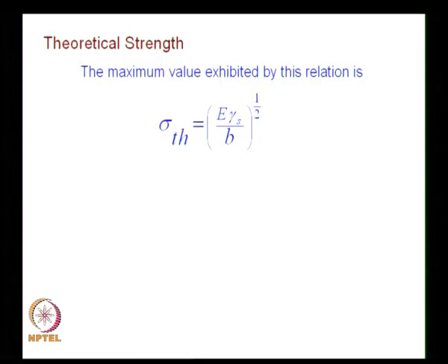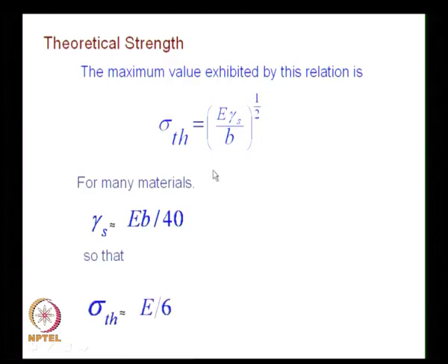People have also found out what is the value of gamma s. For many materials, it is found to be approximately E b divided by 40. So, when you substitute this into this expression, you get a value for theoretical strength. And what is the theoretical strength?